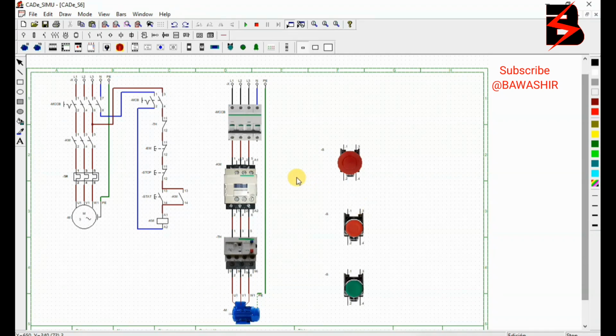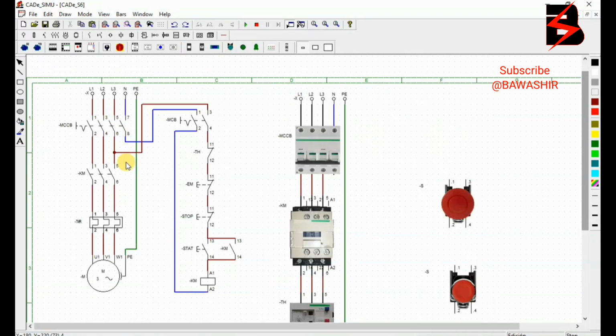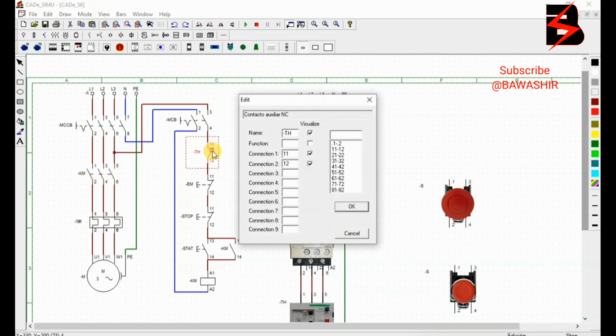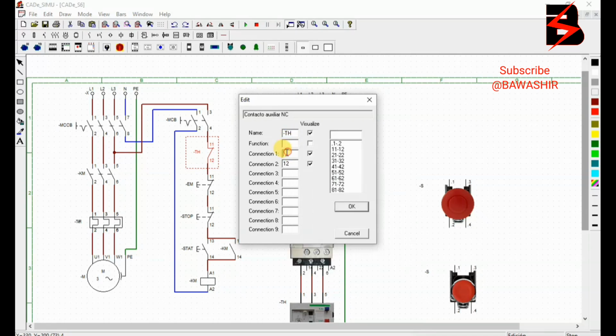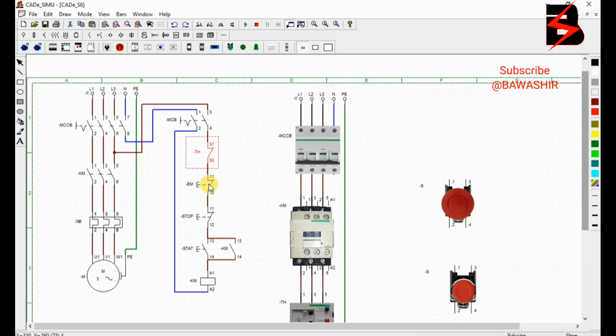So now the other thing also, when we are doing the rewiring, what we didn't consider in the circuit diagram here is what we call the terminals of DC devices. Remember, thermal overload here is always, remind me, 96, 97 or 97, 98 for normally closed. Normally closed, 97, 98. If I'm mistaken, please cross check on the real materials and see. Then the emergency is always 1 and 2.